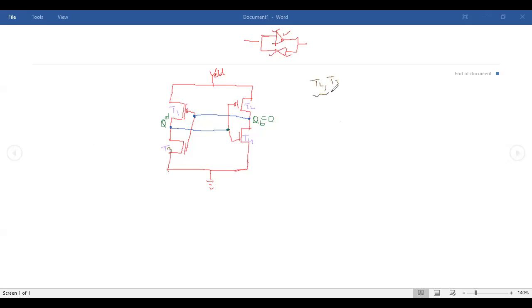I told you in my initial classes that whichever transistors are off, they leak the current. Now, if you see, Q is equal to 1 and QB is equal to 0 is the input over here. PMOS is on with the 0 input and T3 is off. Since T3 is off, that is why it will leak the current. You have one over here.